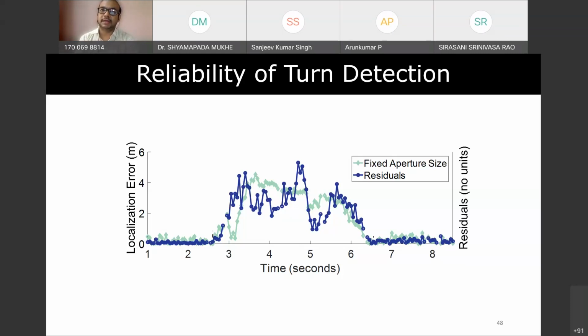In many cases, if a solution exists, we normally slowly decrease the least square error over the iterations and gradually settle on a value. Whereas if your residual does not decrease gradually, or suddenly spikes up, that is a red flag.